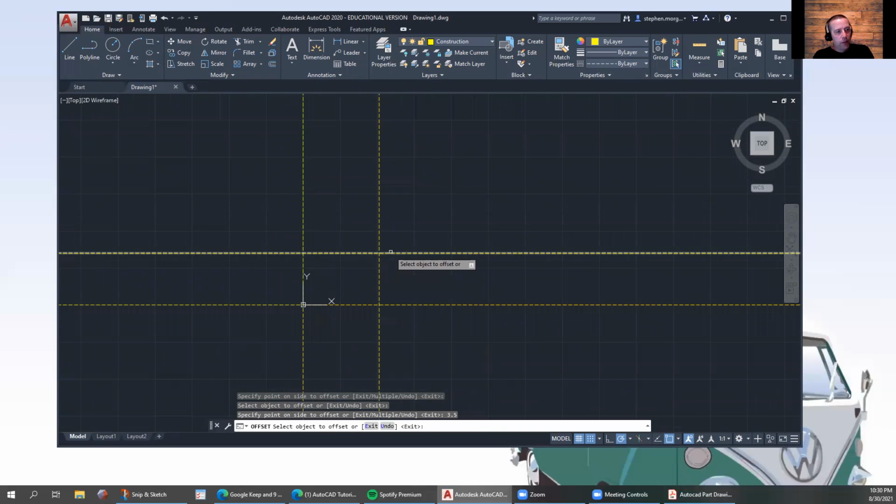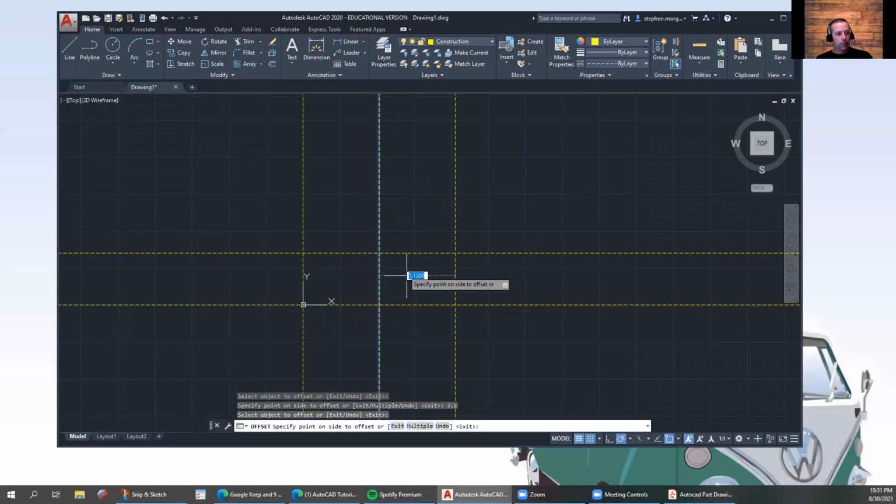Now, between the views, here's our front view, just like in the practice we did in that first exercise we did last week in Solid Professor. We've got our front view. We're going to have our right side view over here, and then we're going to have our top view up here. But in between is some space, and that space is 3 inches. You can always just use 3 inches as the space between. So we'll go 3, enter, over that direction.